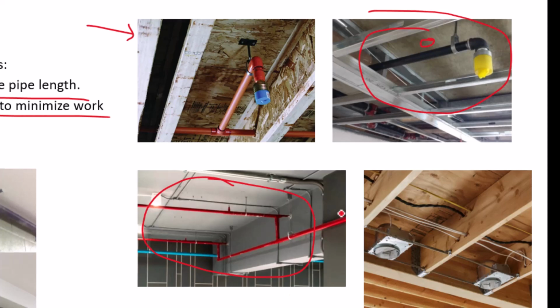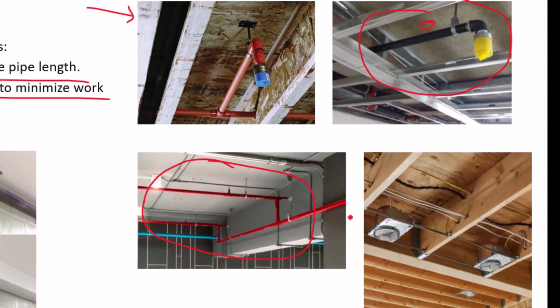And as you are laying out the sprinkler piping between joists, you want to avoid lights because some of these lights extend up into the ceiling by several inches. So you have to make sure that you also account for that when running the sprinkler piping to make sure that there's no conflicts between the piping and these light fixtures.